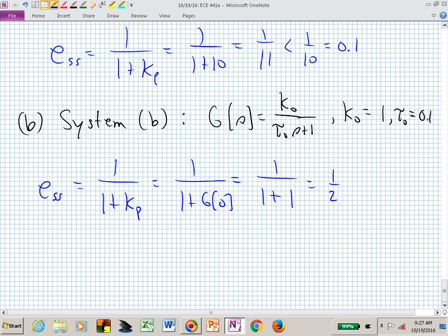1/2. In the previous case, system A, it probably reaches something a little bit more than 0.9 when we wanted it to go to 1. And it had this exponential approach to 1, and it reached 0.9, a little bit more, because its error was less than 0.1. Now, our output is going to 1/2 when we wanted it to go to 1. Our error is 1/2.